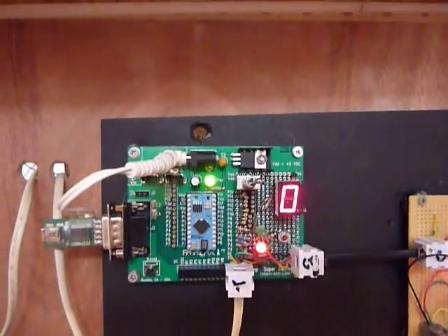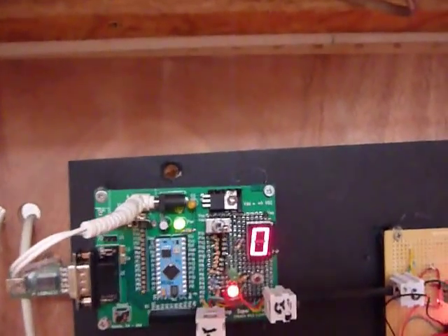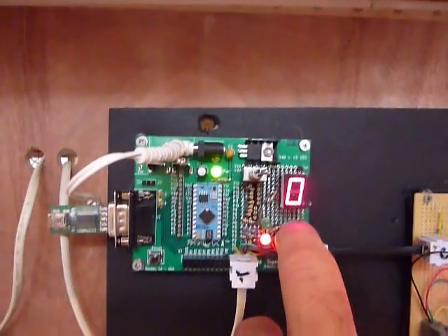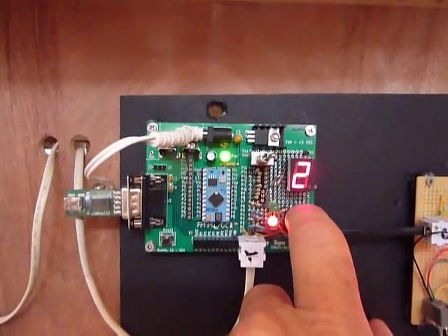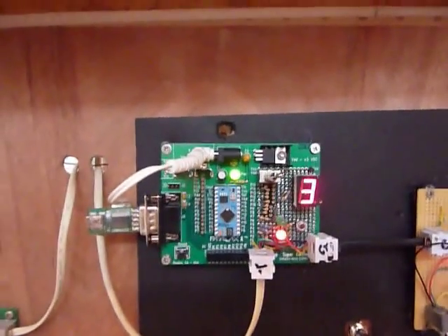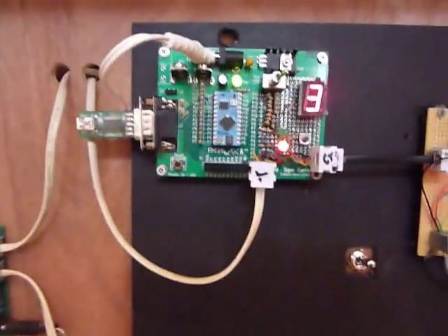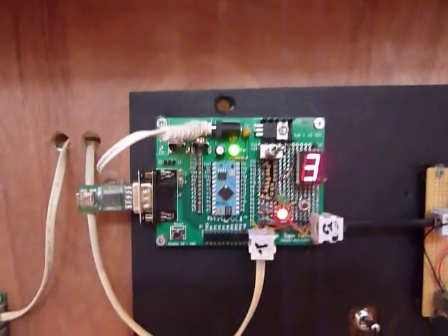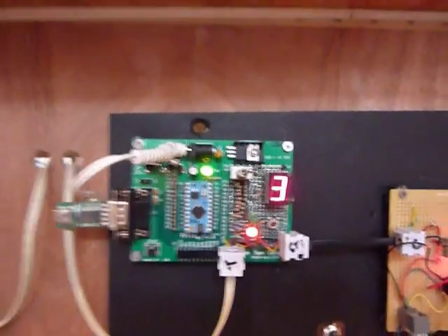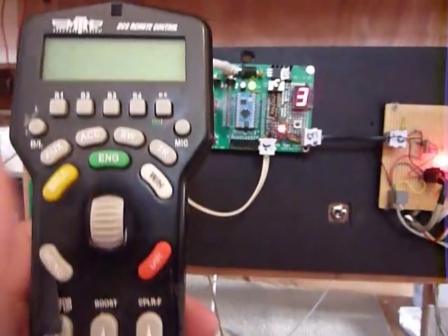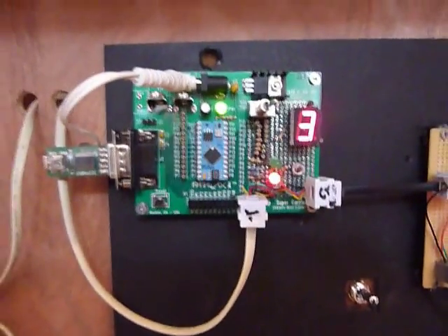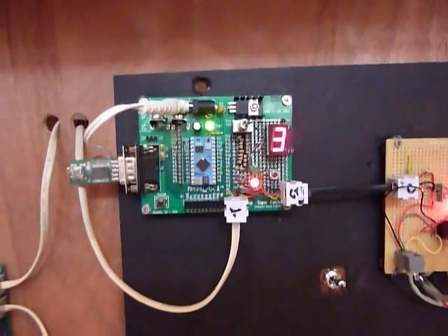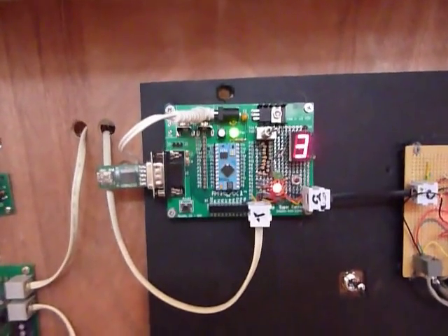It's telling me now that I'm ready to select the engine. So my first engine I would want to enter, let's say I've already got 1 and 2 in, I need to put in 3. I now select 1, 2, and 3. Now I'm set up to load engine 3. I take this toggle switch up here, I throw it over, and now I can take my handheld into my hand, and I go through that sequence I talked about in the signals chapter, where I start with the start command. I'll wait till the green light comes on, then it'll tell me it's time to hit the next button, and so on and so forth, and it just kind of walks me right on through.